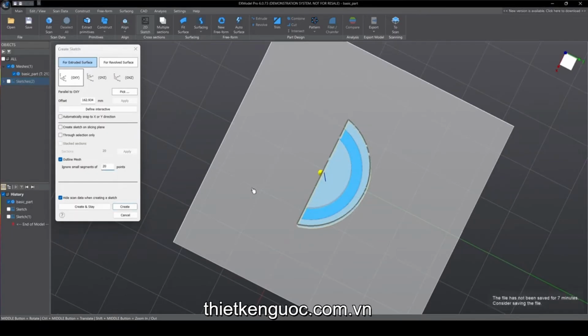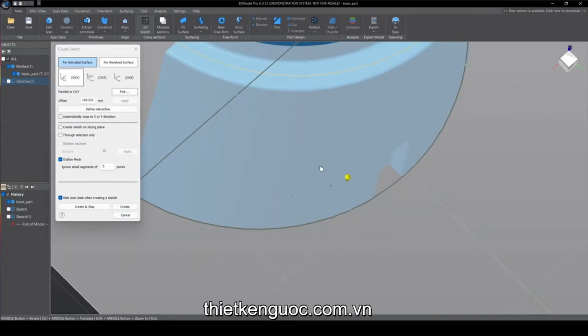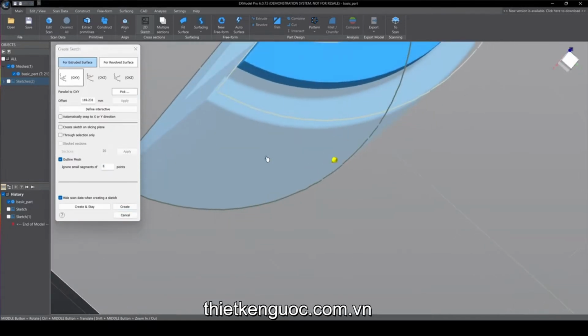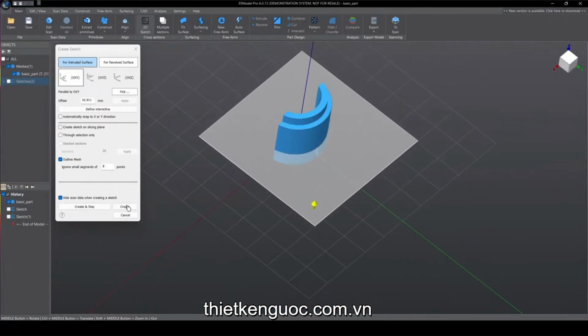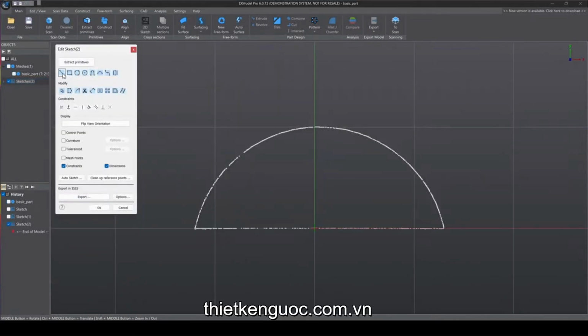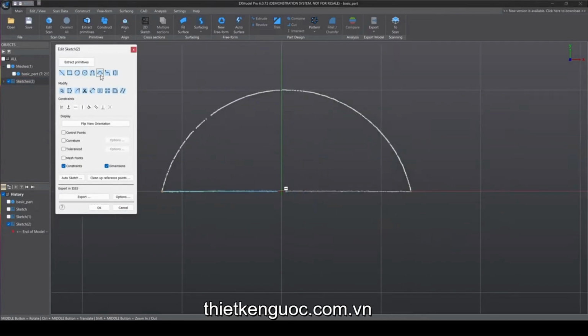You may adjust the small segments points to get better results. Notice there are several noise points floating inside the reference plane. You can eliminate them by using this option. You can click Create, and I will demonstrate by creating a simple basic block from the sketch.